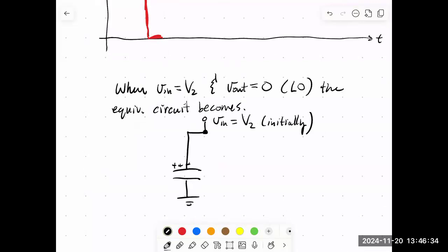The capacitor charged up a bit. So we've got some charge on this thing. And then one side of the resistor is connected to V in, and then we set the other side, V out was low at 0 volts. So that's as if it was connected to ground.